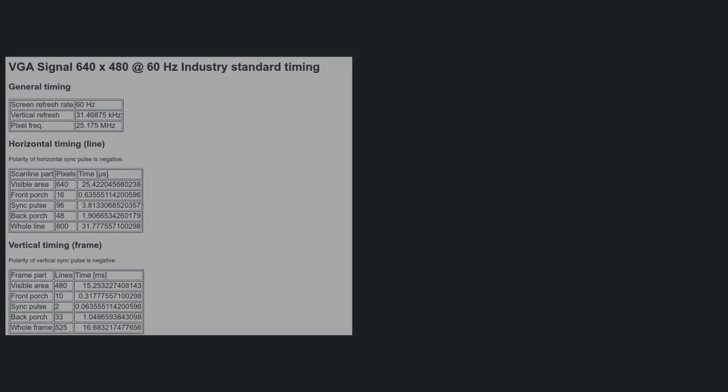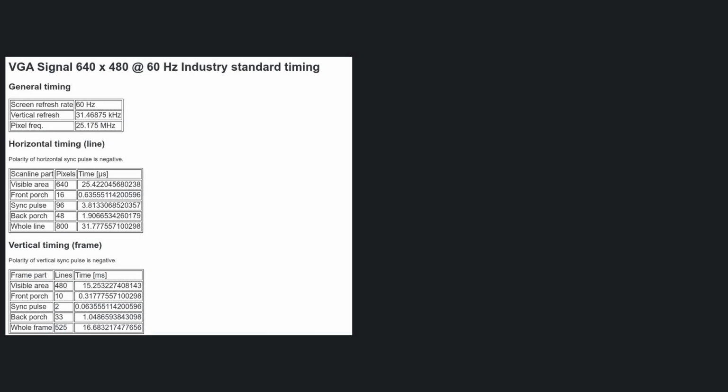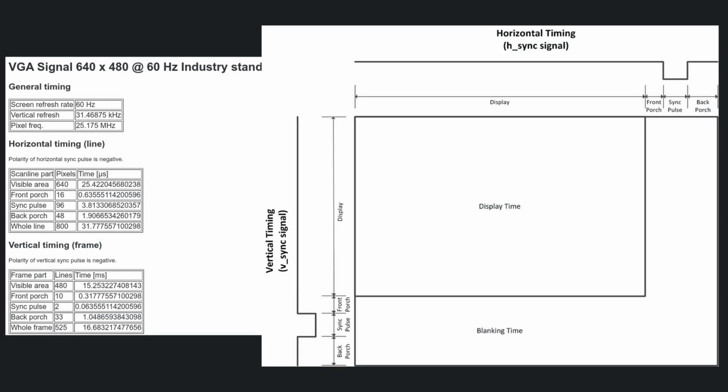This video is already getting absurdly long, so I'm going to blitz through the VGA design, but basically we get our timing numbers from a reference site, and we look at the diagrams to see what the monitor expects for the outputs. We need a V-sync signal to go once a frame for some period of time, and every row of pixels we need an H-sync signal to go low. We also have a pixel clock value which tells us how long each pixel should be on the screen.